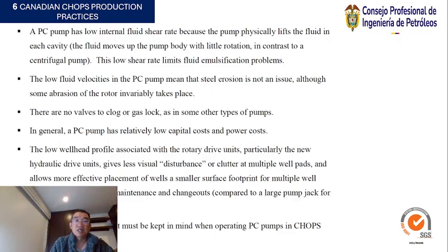A PC pump has low internal fluid shear rate because the pump physically lifts the fluid in each cavity. This low shear rate limits fluid problems.